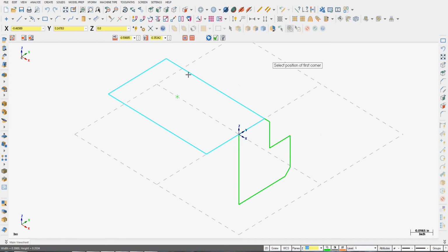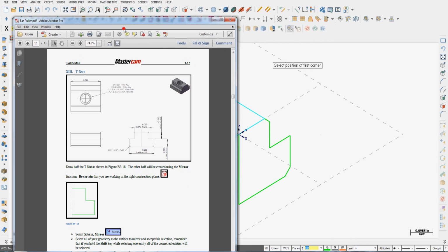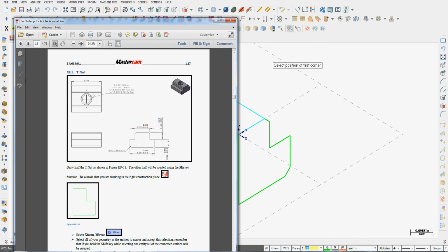So in this case, I'm going to create a rectangle that's 3/4 inches long here in the negative x direction. So in its width column, I'm going to enter negative 0.75, enter. And for this part, I'm creating the rectangle that represents the top of this T-nut.